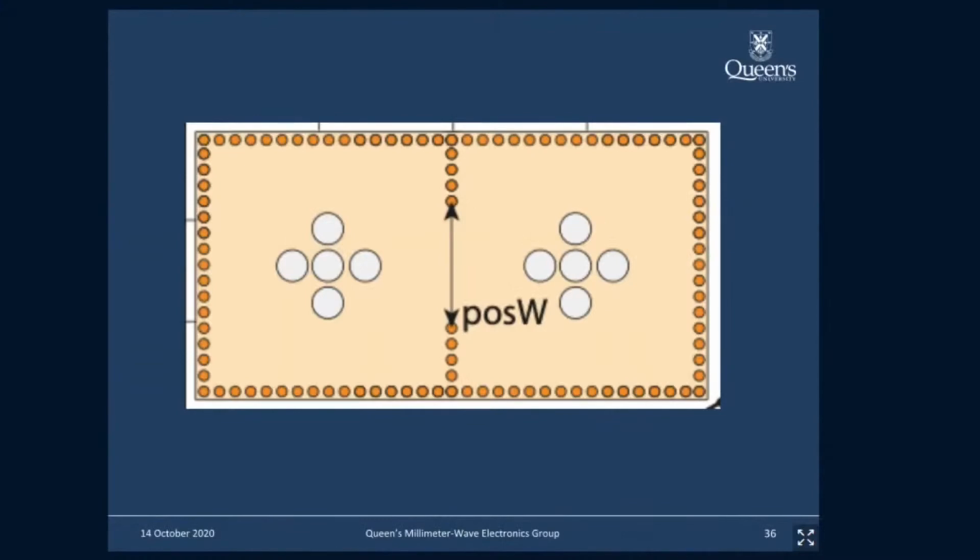So what you can do is you can carve out some pockets in the resonator. So here I now have two resonators, and now they're actually connected together, and I'll talk about that in a minute. But carve out some pockets, and you deposit some fluid of a certain dielectric constant that is different, of course, than the dielectric constant of the SIW resonator. And so then you're changing the field distribution inside the resonator, and then that gives you a change in resonant frequency.